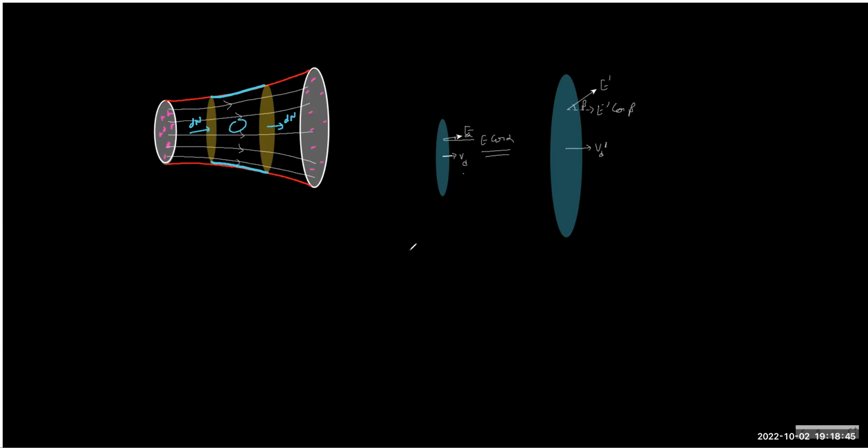So there are two ways. If you have a small area, then you move fast, isn't it? And if you have a big area, then you move slow. In that way, you maintain the number of electrons crossing per unit time, and that is how you maintain the current the same throughout. So in steady state, what we need to remember is that current is a constant quantity, and that is true irrespective of the shape of the conductor.